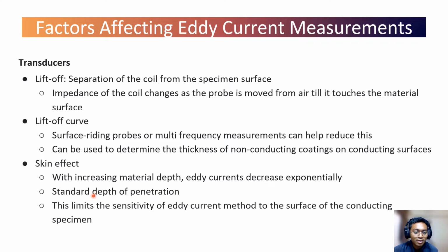Next, standard depth of penetration. This also can affect the result. And skin effect is the limit of sensitivity of the eddy current method to the surface of the conducting specimen.